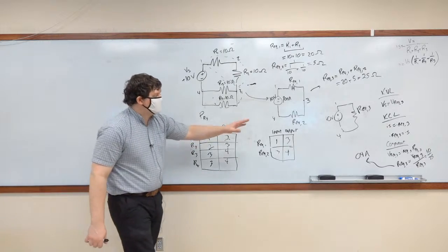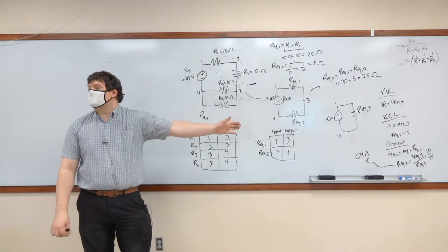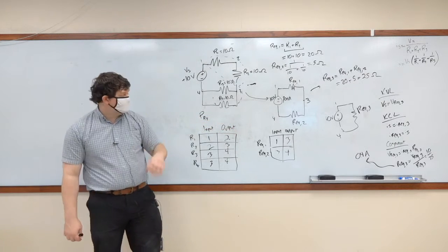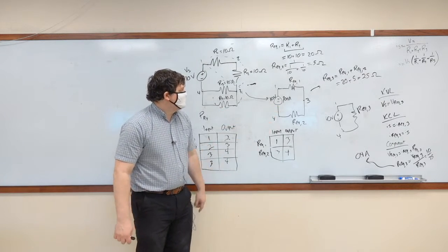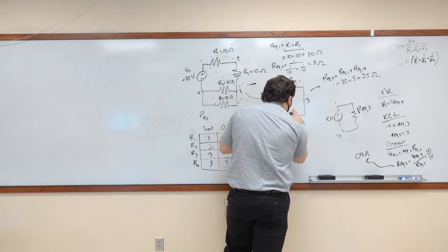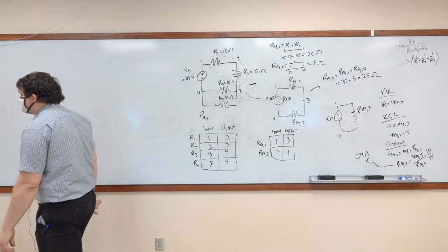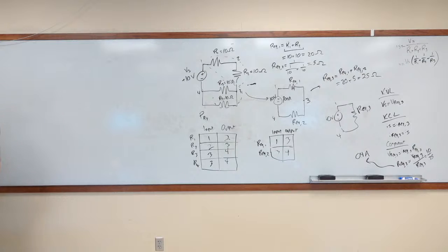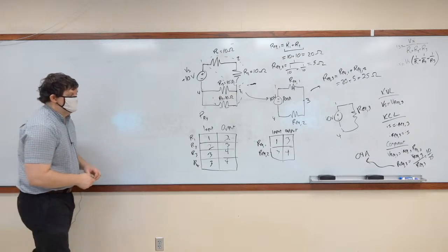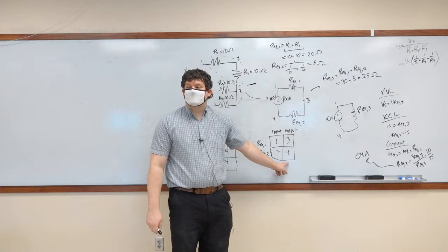And knowing what that current value is of the battery means we can now plug that in other places and get a better answer. So here we know this is 0.4 amps, okay? Which means there are 0.4 amps going through here, which means there's 0.4 amps going through here. With 0.4 amps going through REQ2, what that says is that REQ2 extends between 3 and 4.